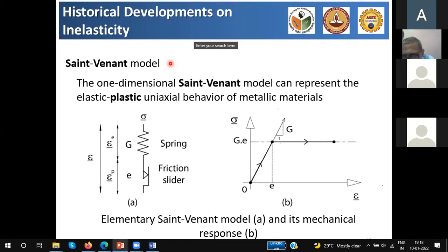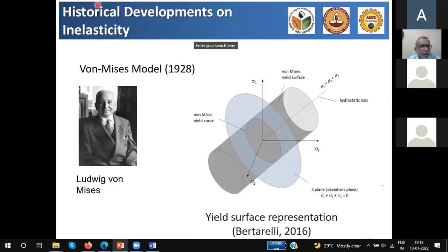So now moving forward from that, you have von Mises, who developed the concept of principal planes, principal directions or principal stresses, and started looking at things in a principal octahedral stress plane. An octahedral plane is something that is equiaxial with reference to the three principal axes. And when you look at the evolution of the material, please note that all of these are discussed in a multi-axis state of stress, even though the tests are done in uniaxial tests.